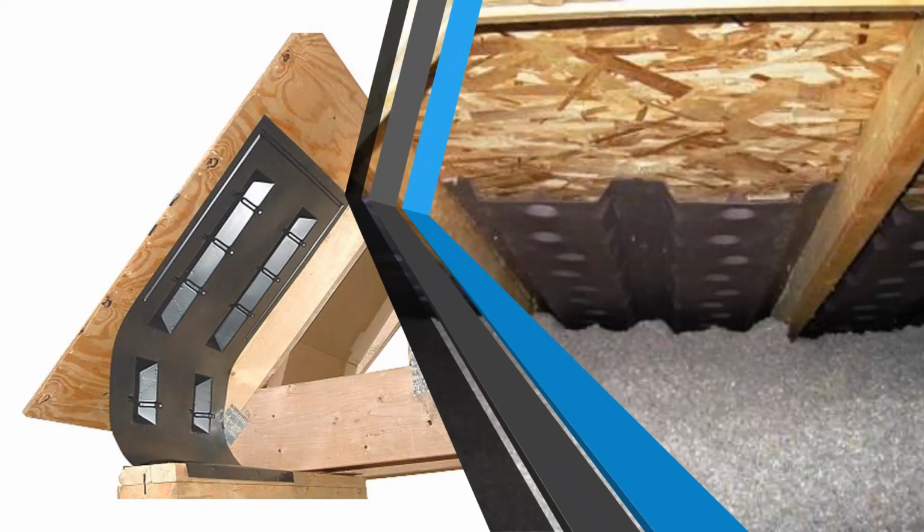I don't know how many times I've seen where they've installed the baffles, they just rolled it down and stapled it to the front of the top plate. There's no way insulation can get over the top plate, and that's a deficiency of the insulation thermal boundary. So it needs to be all the way to the edge so that you can look at it and see blown attic insulation meets the top plate that now meets the wall cavity insulation, and there's no misalignment of the thermal boundary.